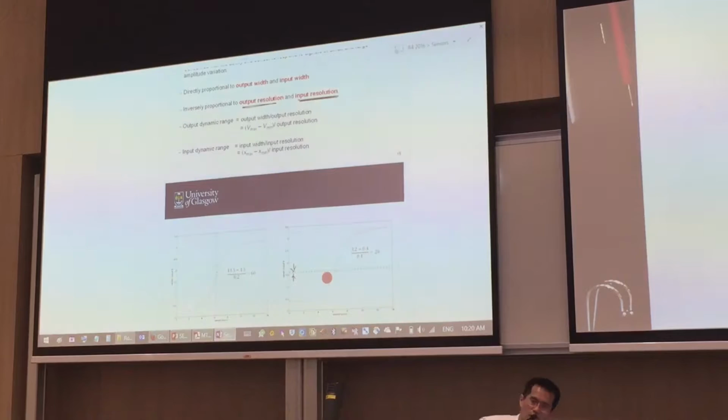So if you look at the voltmeter, right now I took it to 200 millivolts, and I could see the value that's displayed over here, 0.0, for a 200 millivolts setting. That means the resolution for this is up to 0.1.